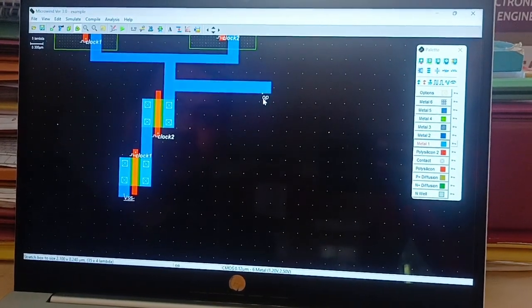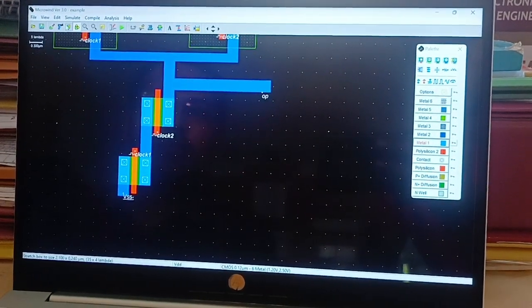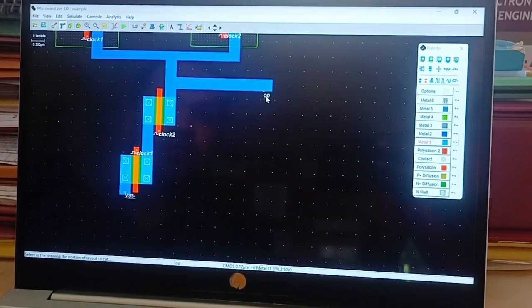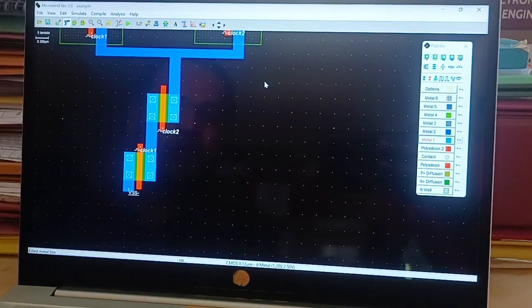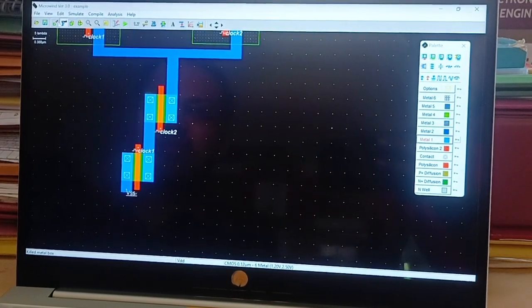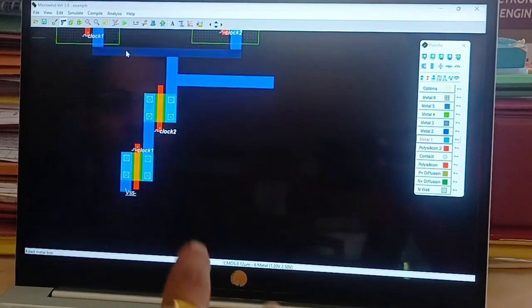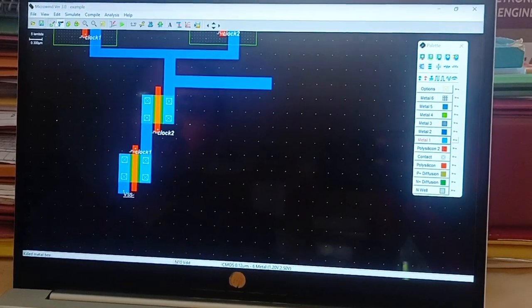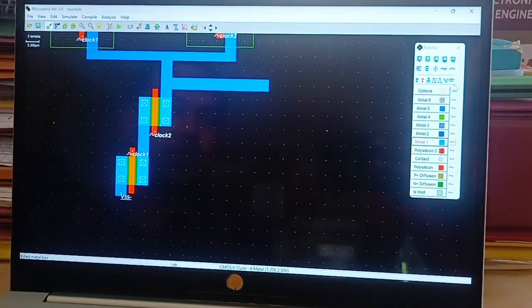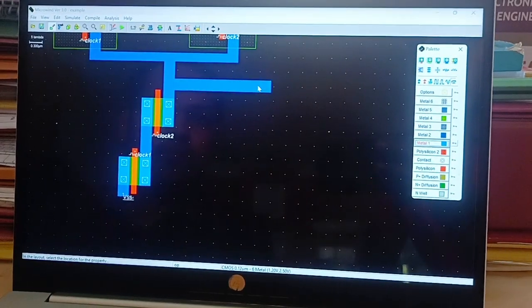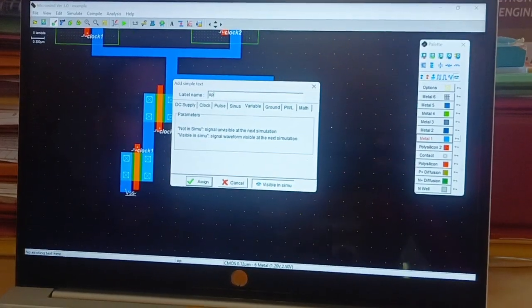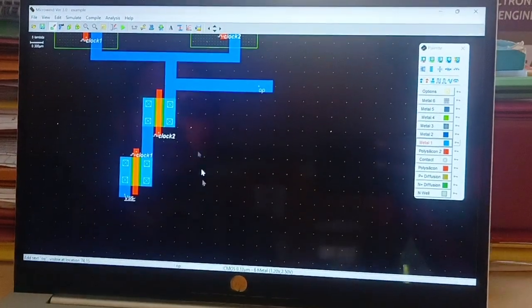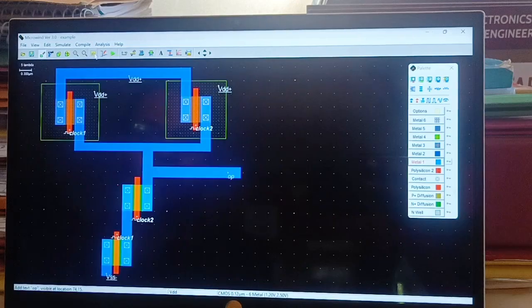Now in this case what happens, output goes out of the metal, so I have to delete it and again place the output. Delete, place an output here. Or gun was selected, mistake. Control U, select a pencil and then select I. Give the name output assign. So after doing this, select all, again go for DRC.